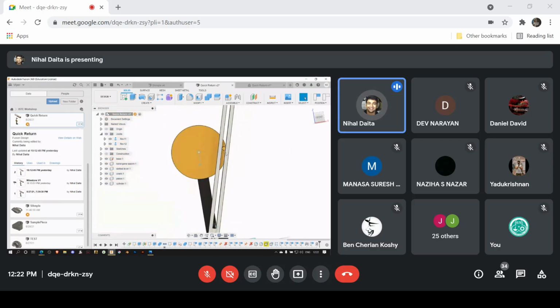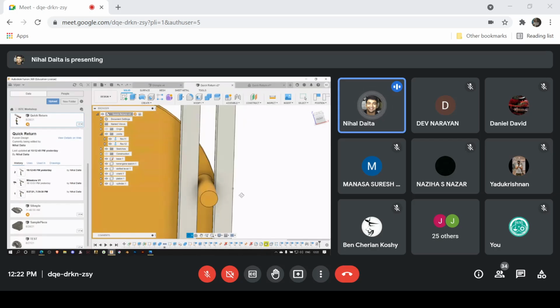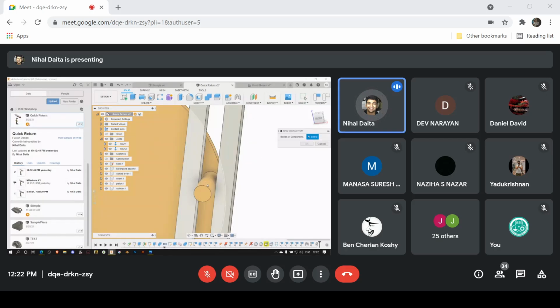The reason I want it there is because there's this thing called contact set, right? So it's always better to establish your constraints using these joints, because contact sets or collision sets actually have to physically calculate each contact with individual faces, right? So it's a bit taxing on your system. A single one wouldn't hurt, but it's better to avoid them. I have to use it here because there is no other way. It's under enable contact sets, right? Then I go new contact set between this face, this body, and this body, and I click OK.